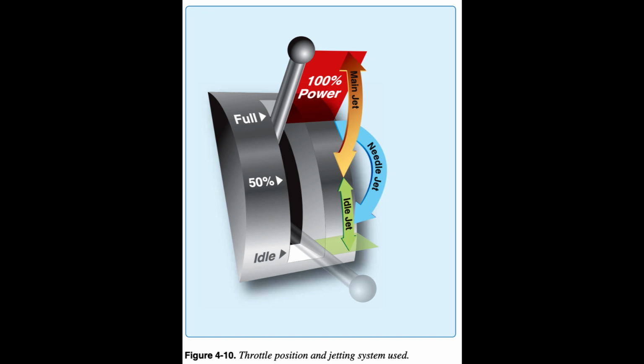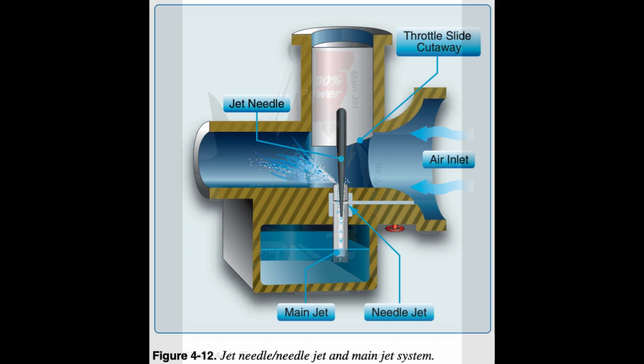About half throttle, the main jet size starts to influence the amount of fuel mixed with the air, and this effect continues until it is the main influence at the highest throttle settings. Figures 4.10 and 4.12. End of page 4-9. Two-stroke carburetor jetting for proper mixture.